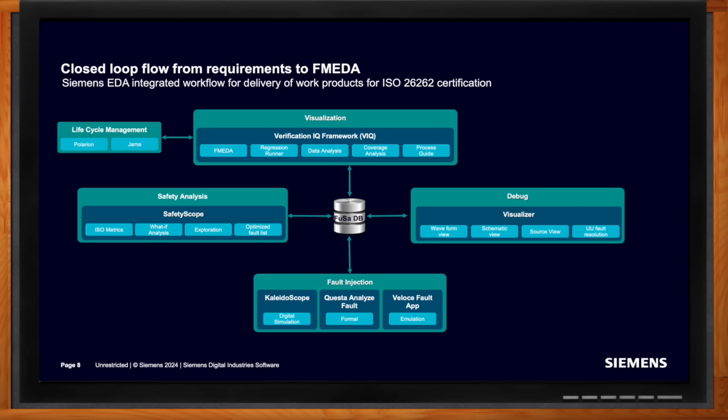There's a lot of things that are outlined by the ISO 26262 standard about getting ready to develop a safety critical IC. And then really from there, you're going to start creating your FMEDA, your failure modes, effects, and diagnostics analysis, which is really a mapping of your design to the failure modes, to the safety mechanisms that are designed in to mitigate those failures and mitigate faults, right?